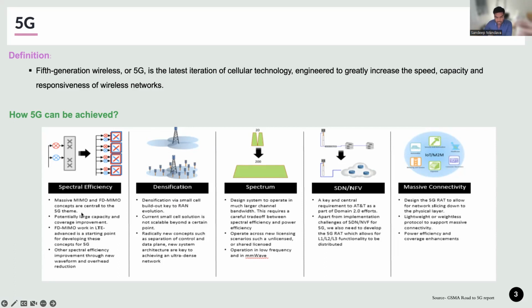And this also enables full duplex communication. Right now, if you have a channel that's sending information, and that channel needs to become vacant for it to receive information also. But with massive MIMO, you can probably use the same channel for sending and receiving, because different antennas would be doing that for you. So you can do full duplex communication at the same time, which obviously increases bandwidth.